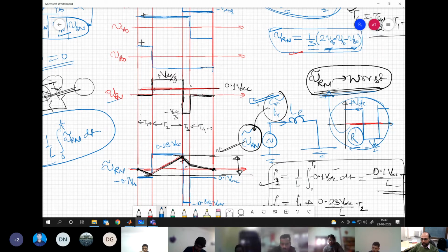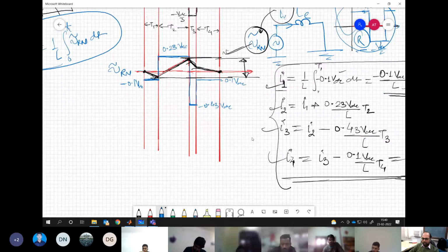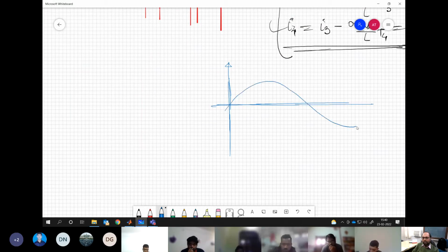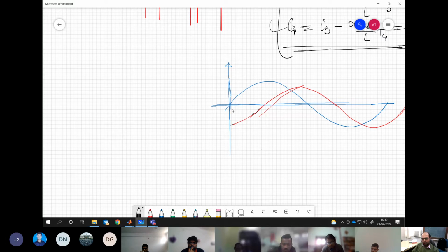So once you try running the system or the simulation, a very interesting thing you will observe is that, say, this is your voltage and you try to have some current, let's say it is lagging by almost 90 degrees or so. What you will observe is that on this current, there will be ripple everywhere. But wherever this zero crossing comes, suddenly the ripple will be highest. So at this point, it will be something like this. At this point, it will be something like this. In all other places in between, it will be a small ripple somewhere, but suddenly it will maximize.